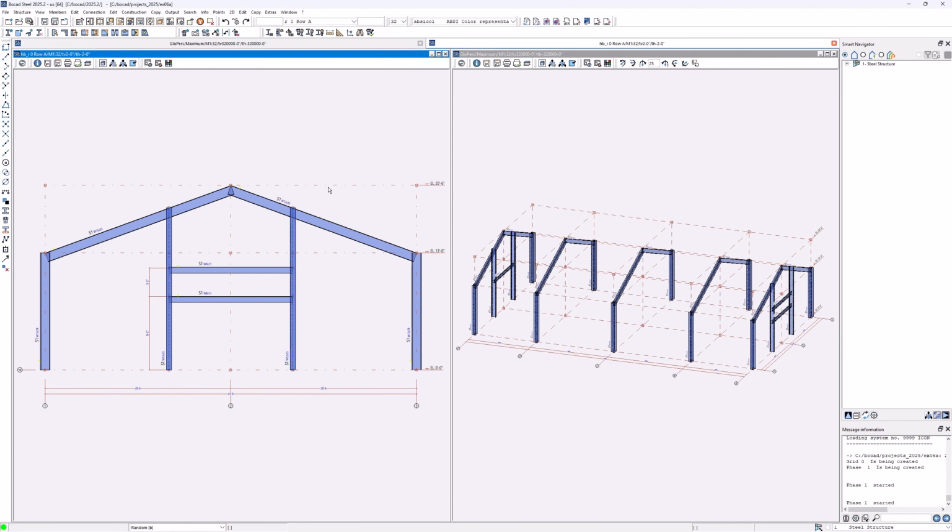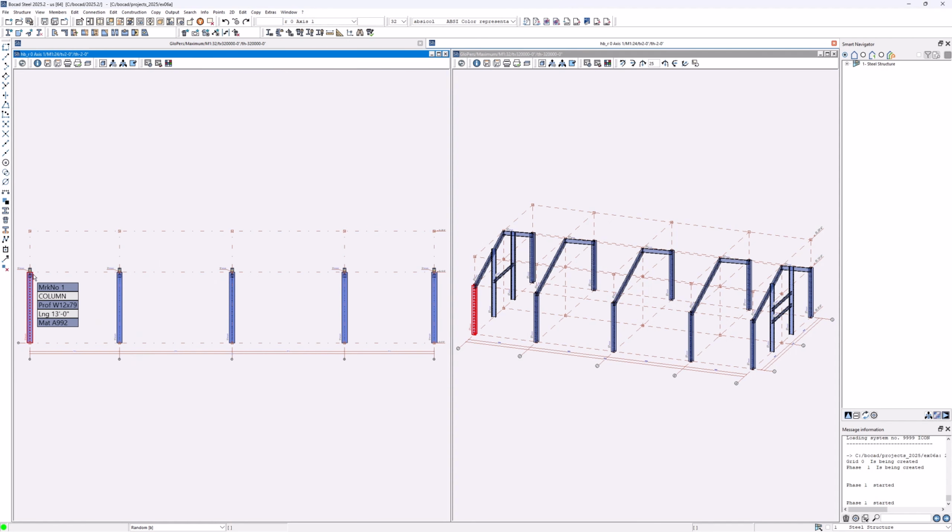The text will become a bit bigger compared to the elements. In the next step, we can create some of the girts, and there's various ways to create the girts. I go into this view, I set out either my offsets or my points, and I create the girts, but I have to consider the fact that I'm on the axis right now, so I'll be right in the middle of the column, and I would have to consider an offset.